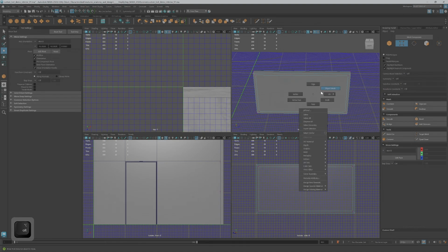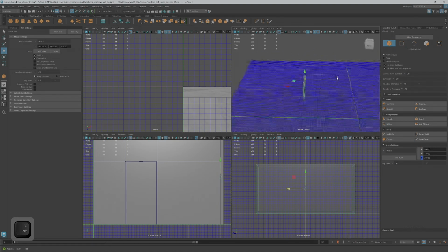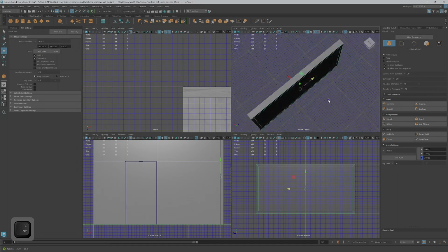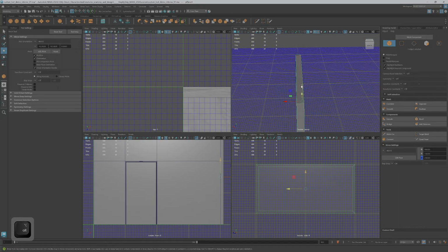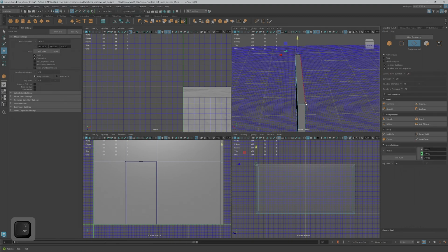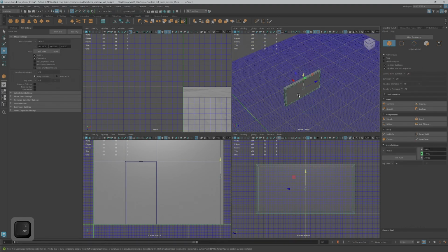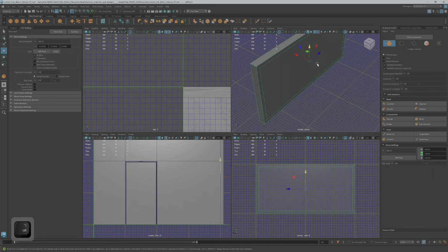I think maybe a good time to do a freeze and delete history on this thing. So we'll go grab these edges and go right around the middle. Actually, let's see, this should work okay. Let me go ahead and just drop this again to the outside. So turn off the snap. Maybe the snaps are messing it up too.